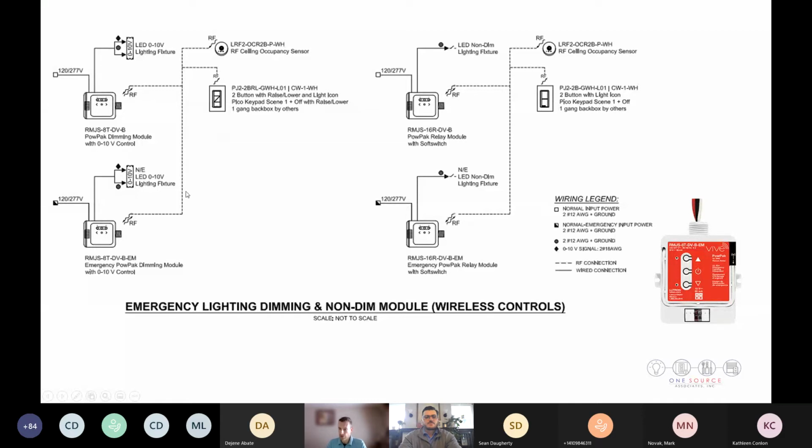and you lose power for 250 milliseconds, this emergency device, the relay, closes and goes to full output. When the emergency is restored, it goes back to normal operation. But whenever it's in emergency operation, it will not accept a signal from an aux sensor, a wall control, or a daylight sensor. It stays in the emergency mode, regardless if it sees occupancy or someone touches a wall control.